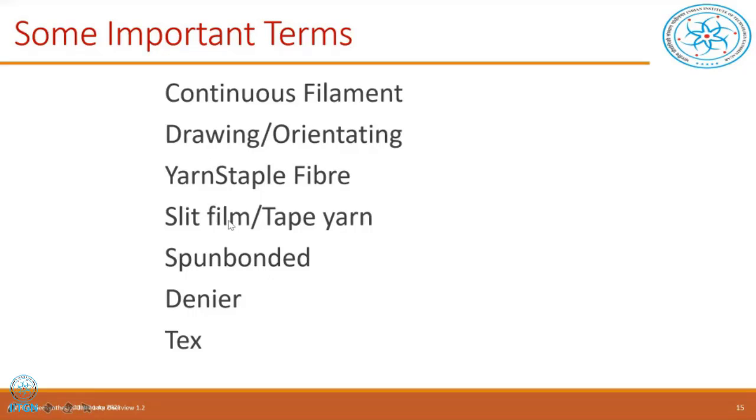The other thing I mentioned is that normally all this I have shown you, the filaments are rod-like, basically very fine rods. And that is how we extruded them. But there is another process of getting this yarn also. This process, when we go to membranes, we will tell you. So instead of taking the extruder, we are going to pass the same thing through hot rollers. That means a sheet comes out. Then the sheet is again made into smaller units. We'll see the figures of that later. And finally, when you get to the finest size, I will show you that sample also. It will become a very thin kind of material.